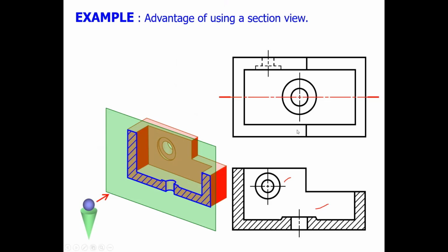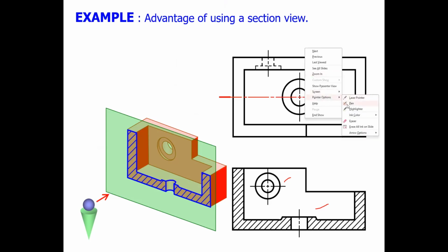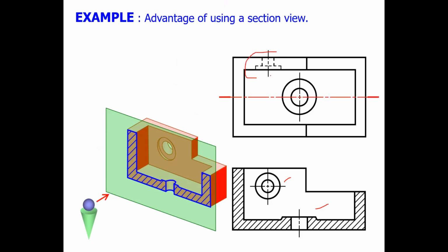When you do sectioning, I didn't say the top view. Yes, on the top view you have hidden lines; this one definitely has hidden lines. The top view is not involved. On the top view we have the section line, but it is not the section view. The section view is here at the bottom, the front view. On the front view we have section lines. Can you see a lot of lines slanting at a 45-degree angle? These are what are called section lines. So on your front view, we don't have hidden lines.